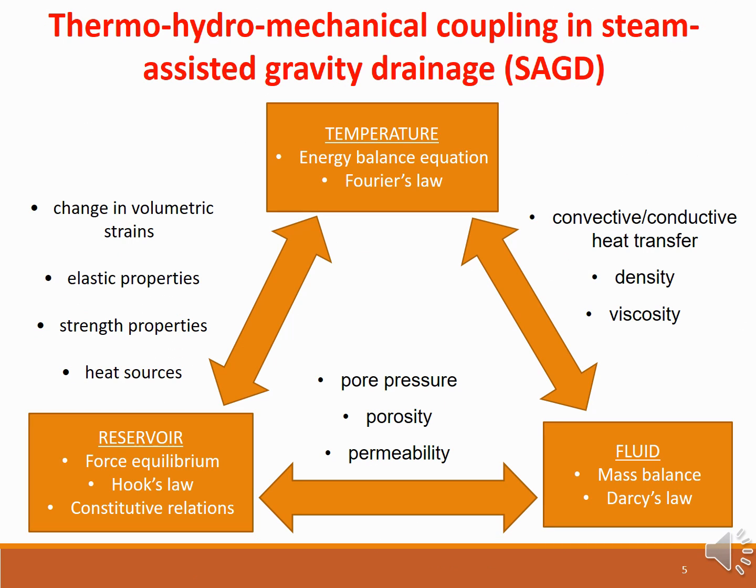Accurate description of this method requires simultaneous consideration of the flow, thermal, and mechanical processes. Usually coupled THM processes in geological porous media are governed by the momentum, mass, and energy conservation laws, which are supplemented by state laws and constitutive equations.